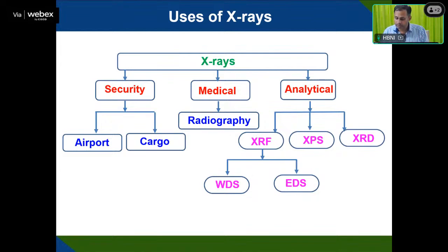In the X-ray diffraction technique, we will discuss conventional X-rays, its sources, detectors, as well as its principle, some examples, its analysis, Rietveld analysis, and then the interpretation for phase identification, as well as particle size, crystallite size, strain, and how different factors affect the X-ray diffraction pattern. In addition, thin film XRD, like grazing angle XRD, synchrotron XRD, and small angle XRD, all those things we'll discuss briefly in the next two classes. After the X-ray diffraction technique, we'll go to the other techniques.